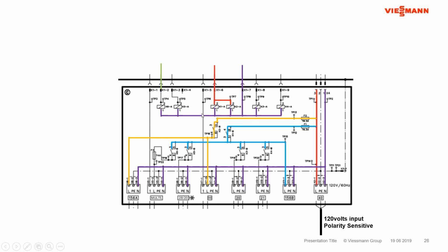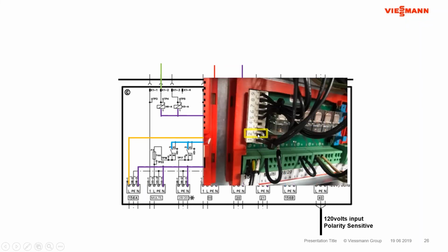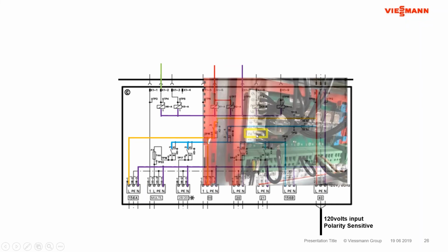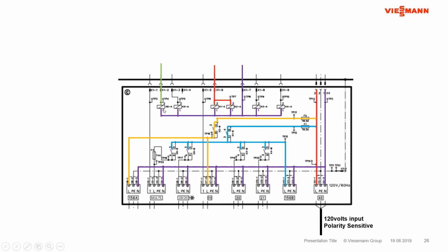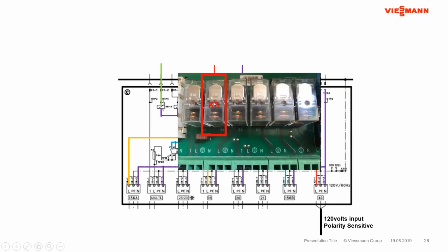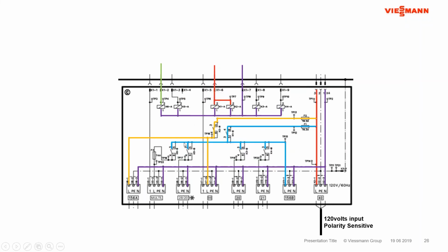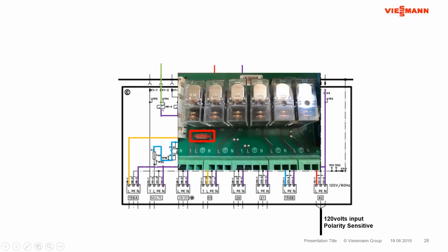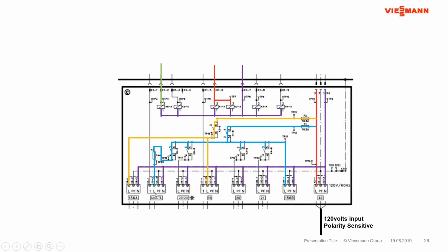So now that we've moved through the 53L contact, we're going to be coming down here on X1-2. And once we hit this particular connection, we are energizing the K6 relay. So K6 relay closes, and now we power through a little 4-amp fuse, and we're going down to the L on our multi-plug.